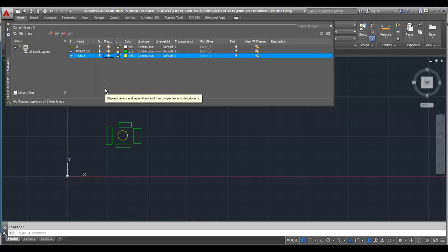Your dimensions are all in one layer, your notes are all in one layer, mechanical parts might be in one layer, windows, doors, anything that you might want to separate at some point so that they're not so confusing and you can use the drawing for multiple purposes, we're going to put into separate layers, and we'll look at that a little bit later on.